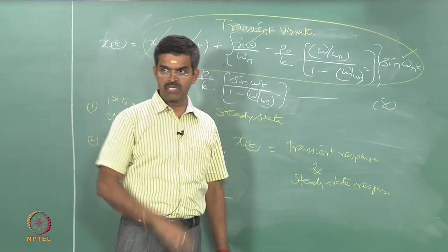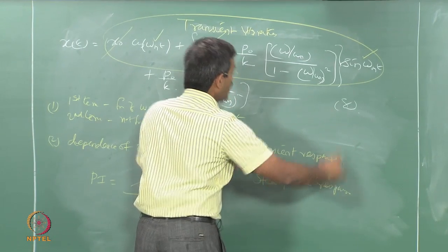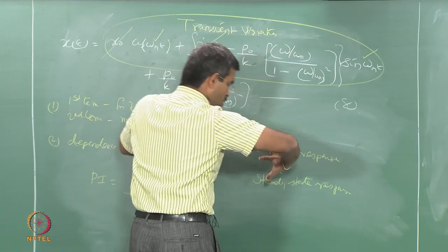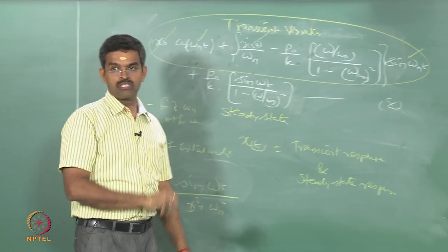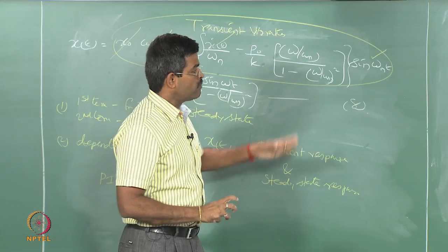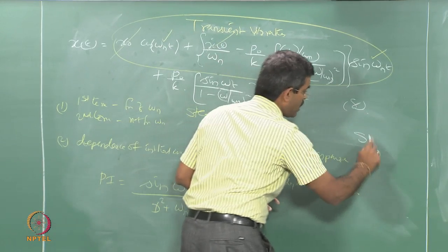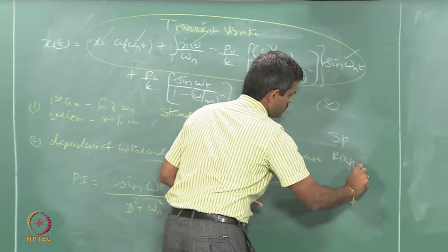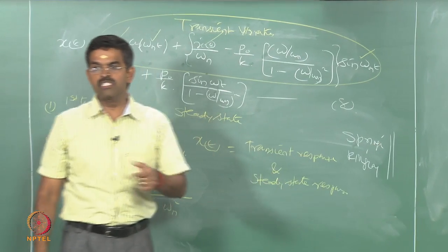Now, one may ask a question here, is the transient response not important? Why do we actually handle this? Can we deal only with steady state? The answer is no, because in offshore structures, unfortunately, talking about fluid structure interaction, transient responses like springing and ringing play a very major role in causing instability.